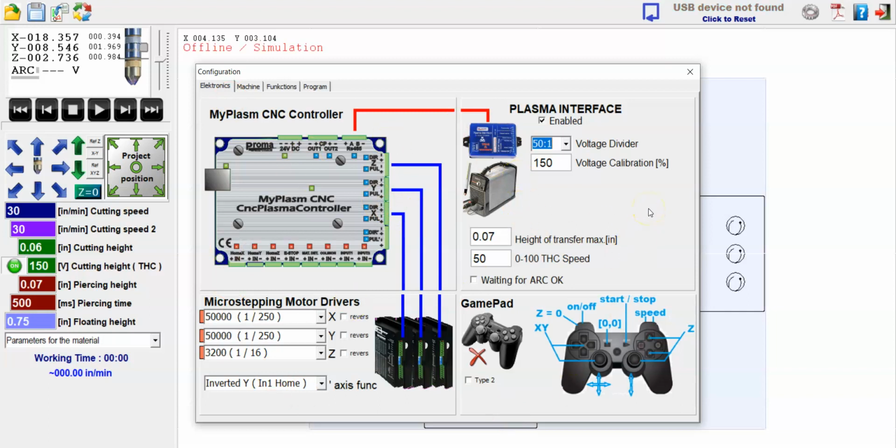However, based off of the different producers of stepper motors, some stepper motors may have a different direction. So what we want to do is make sure that we are in fact getting the proper direction out of our motors. One way to do this is we can always reverse the direction of the motor. If the z-axis is going backwards, we can click on the reverse, and that will reverse the z-axis. Similarly with the y-axis, if it's running opposite, so if you hit the up key on your keyboard, it should move away from you.